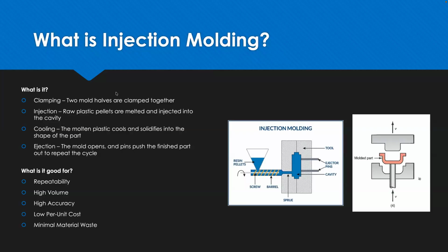This is used for high volume manufacturing typically. It can be highly accurate and a pretty cost effective way of manufacturing. But again, when you need those high volumes, anybody who's dealt with this also knows mold costs can be quite expensive. So you've got to have your reason to invest 10, 20K, maybe 100K, depending on your part and the type of tool you're doing. So you want to be running a lot of parts. But that's a quick overview.